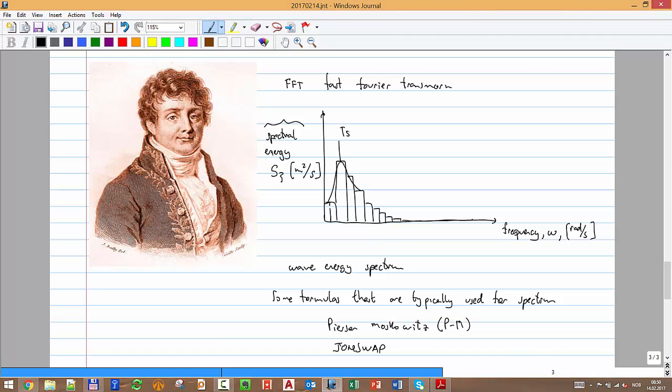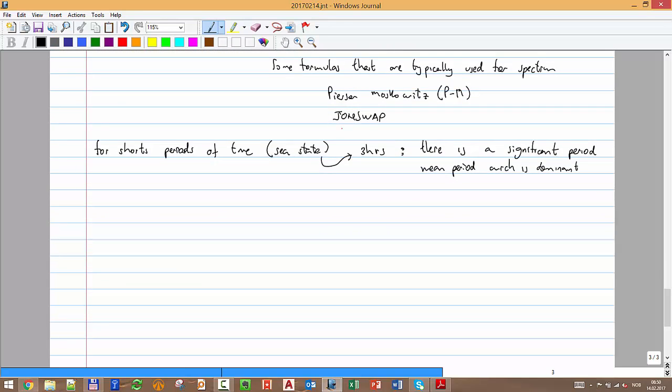Well, you have to convert from frequency to period, but that will be my dominant, my mean period. And I can characterize in these 3 hours most of the waves with that T. But that's only if I look at 3 hours. The significant period is usually considered constant. So we can approximate, if it's really short, 3 hours, one sea state, that you can just report one frequency, and that's enough to characterize the whole 3 hours.